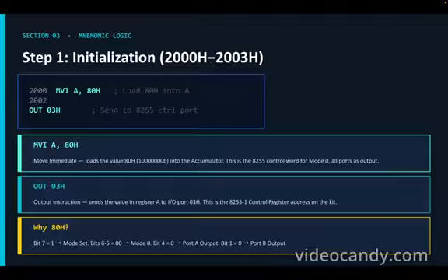What OUT does is it takes the output which is generated by our 8085 and passes it into the module. This line is what sets that up. So MVI A starts the input processing and the OUT 03H starts the output. We are setting the input output ports for now.